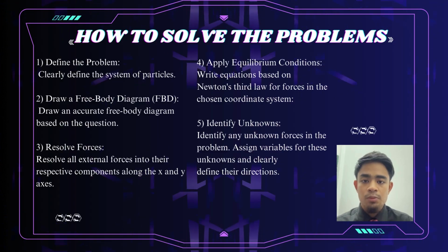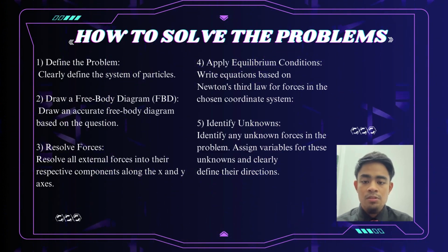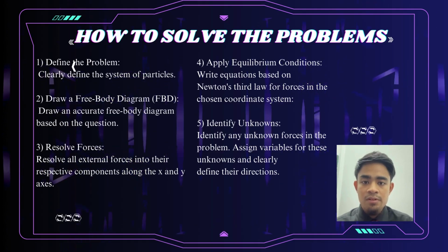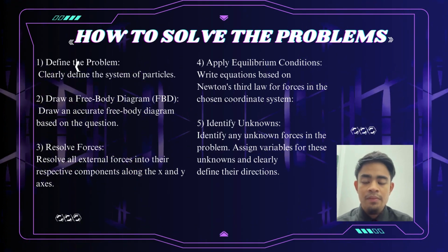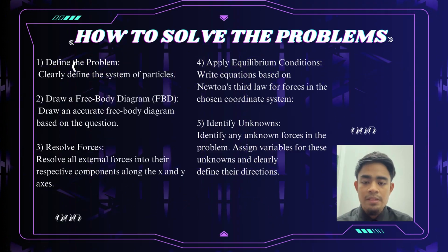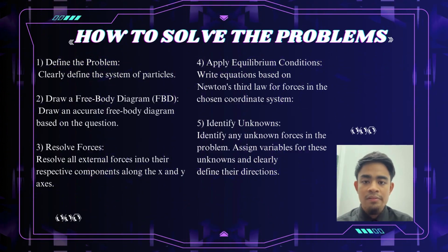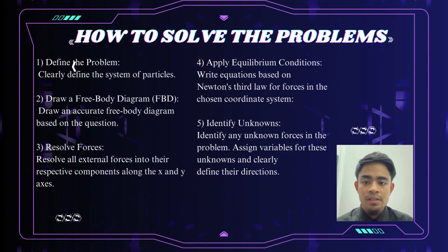First, we need to define the problem. We need to clearly define the system of the particle and understand the external forces acting on it. The second step is to draw a free body diagram, which is FBD.